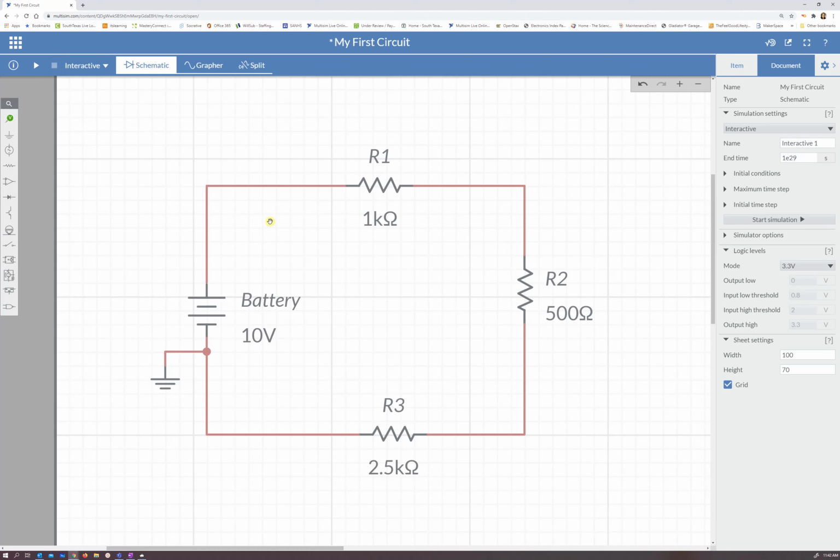And I'm going to measure some values. Now, Multisim Live does not have multimeters the same way we have them for our handheld measurement device. But they have these little probes right here on the top left, the analysis and annotation. There's voltage and current, and other data and digital probes. I am going to use the combination of voltage and current at the same time, so I can measure both at the same time and not have to worry about putting multiple probes.